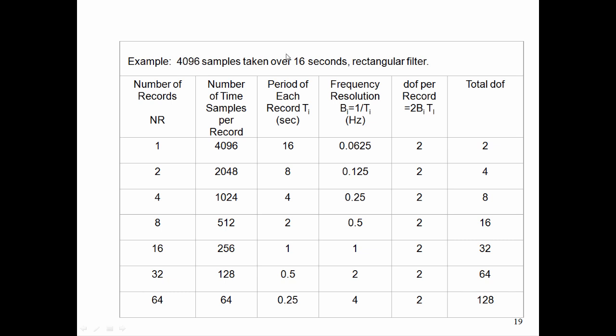So anytime we're going to do a power spectral density calculation, we need to apply some critical thinking skills and determine how we're going to process this data. And I'm going to give you a little soapbox type comment here. If you're already using power spectral density software, and it's just a turn the crank type software, and you are not prompted for this type of a decision table here, that's not the way to go.